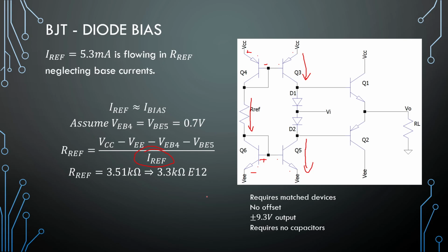And if we divide that by our reference current, we get 3.3 kilo ohms for our reference resistor right here. So these current sources are quite easy. It's just Kirchhoff from top to bottom and know that it will mirror whatever is in these transistors right here.